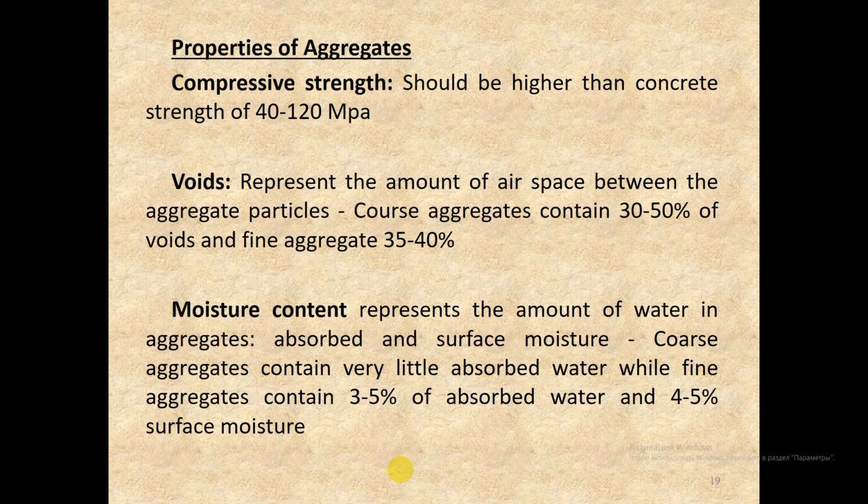Aggregate should be stored in as large a pile as possible, as this helps to ensure an even distribution of moisture content throughout the material.